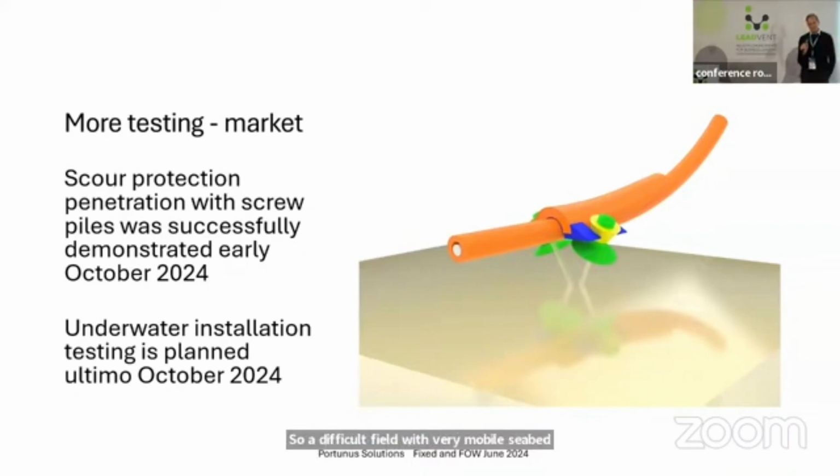In such a project, we would use the same 120 millimeter diameter thread, but most likely the length of the screw, because we have threads in each end of the screw, would end up at either 18 or 24 meters. So we would keep extending the screw until we actually get 33 tons of anchoring strength in the screw.